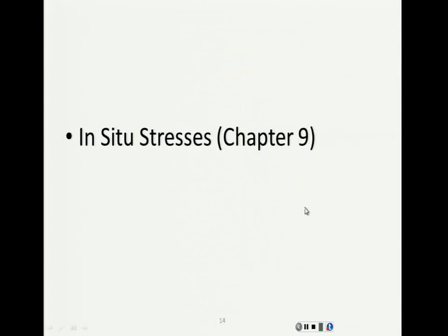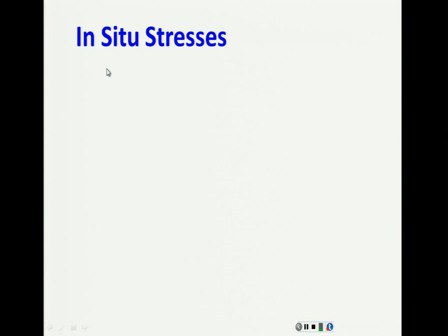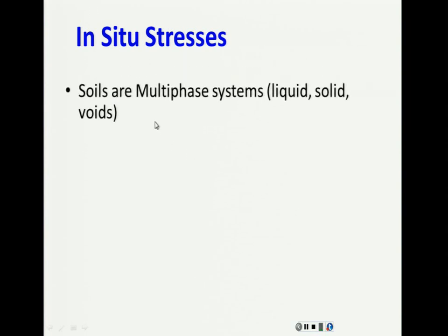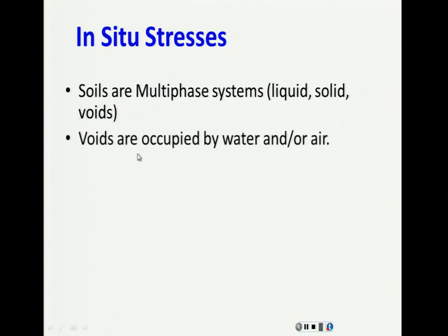Chapter 9 in your book. And this is a concept that you basically know from other courses before geotechnical engineering, where you're just applying the concept to soil in a particular case. In situ stresses, first of all, you have to remember that every type of soil is a multi-phase system because it's integrated by liquids, solids, and voids. The voids might be either occupied by water or by air or by a mixture of water and air.